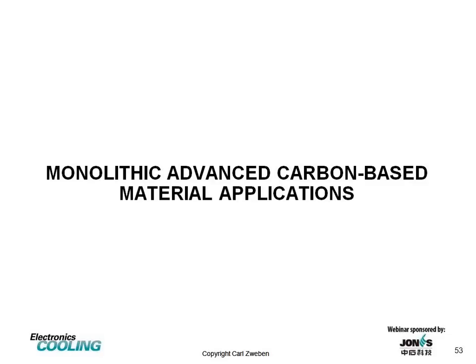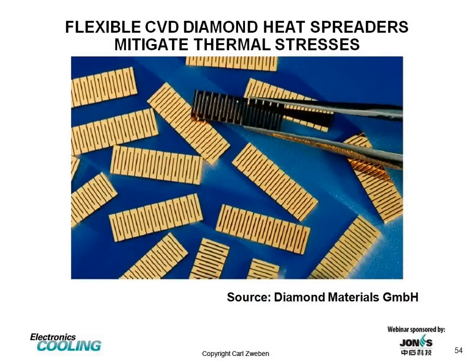Earlier on, I talked about properties of CVD diamond made by chemical vapor deposition, which has a coefficient of thermal expansion in the range of 1 part per million per degree Kelvin. And that's actually lower than we would like. We want the range of 2 to 7, and that low coefficient of expansion can actually cause tensile stresses during cool down from solder operations, for example, that cause tensile stresses in semiconductors and ceramics.